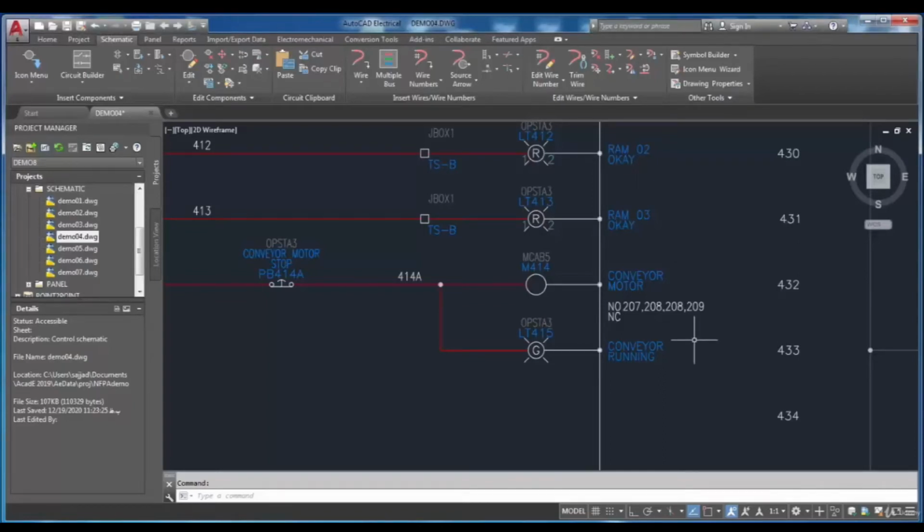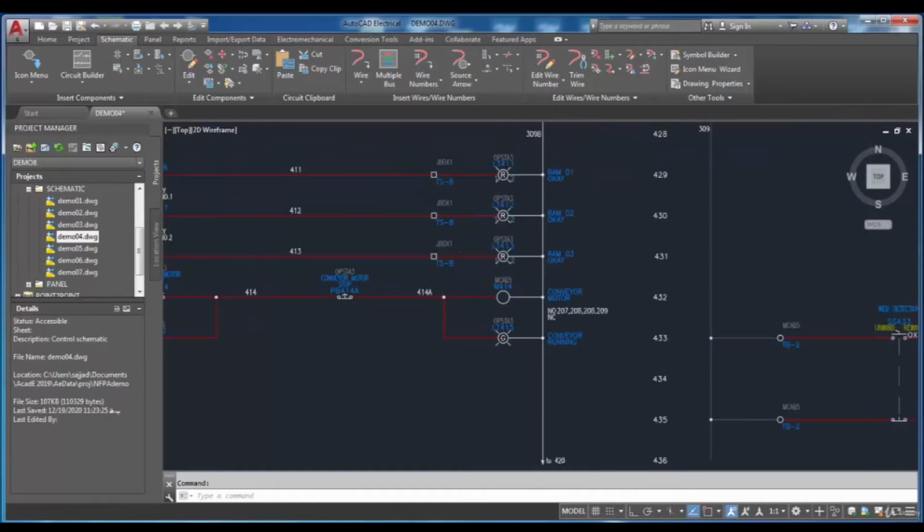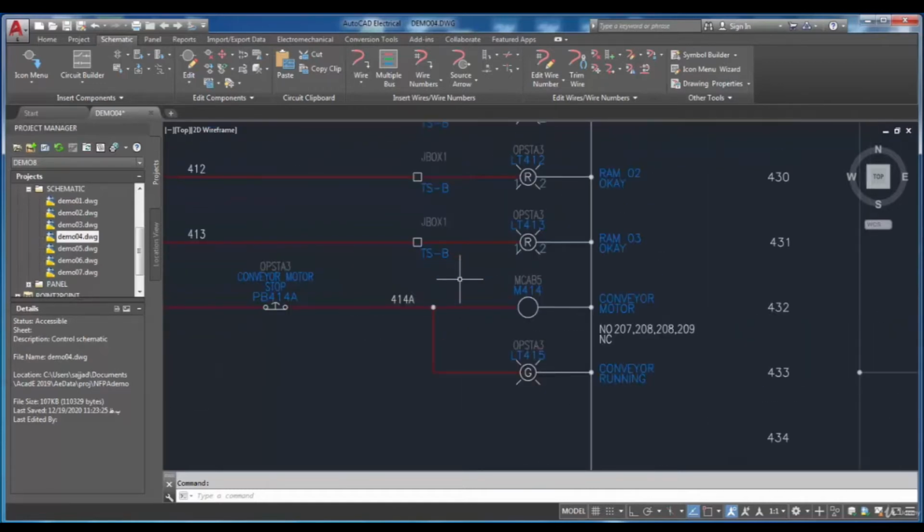You will often need to solve problems with shorted wires or wires which are not connected to each other. Therefore, in AutoCAD Electrical, it is possible to check a wire segment or highlight the wires of a wire network. I mean that you can follow the wires segment by segment automatically and solve the problem. Okay, now let's see an example together.